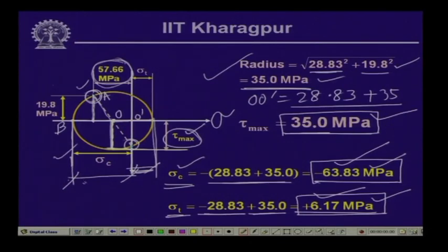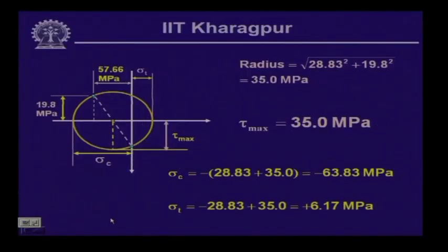These are the values at that particular point when the bracket is subjected to tip loads, one in the vertical direction, another in the horizontal direction, which is parallel to AB. These two forces produce the stresses at the support, which give you the maximum tensile, maximum compressive and shearing stresses of the magnitudes we have calculated here.